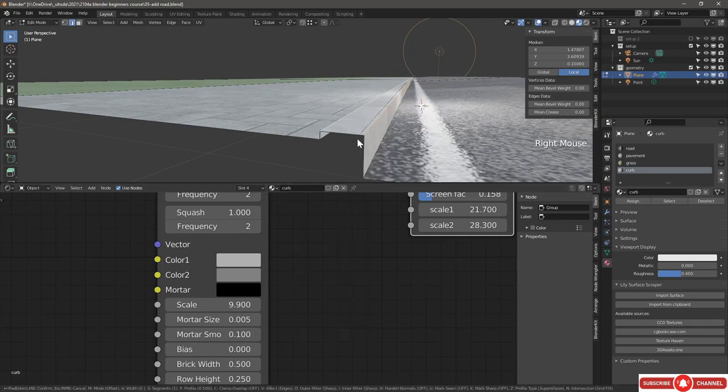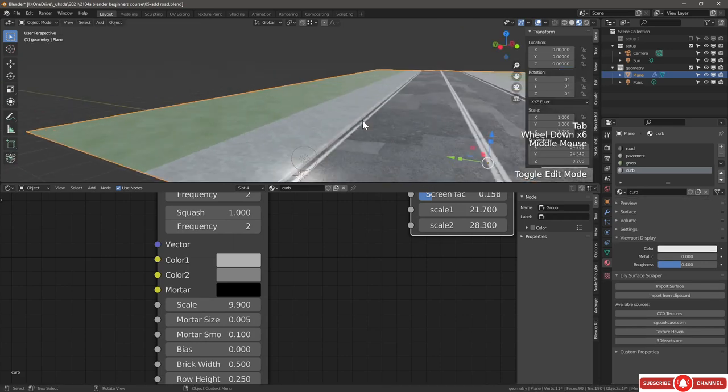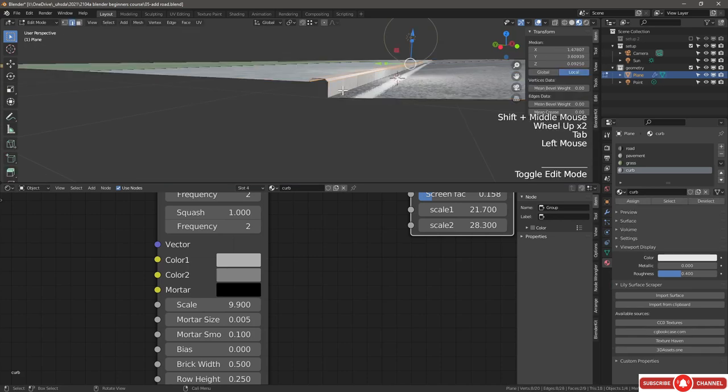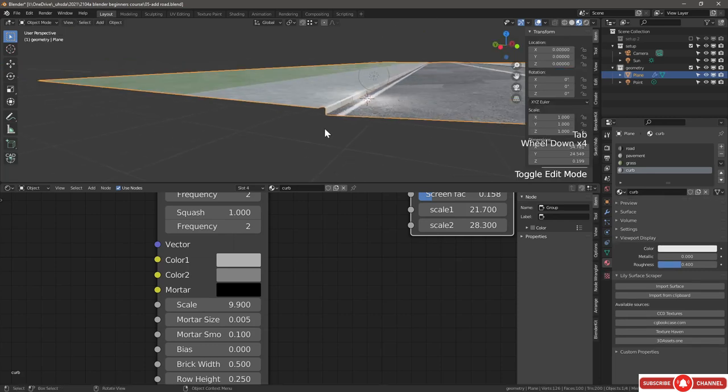Right click, bevel edges. And it's going to start beveling, or we can just type something like 0.03. That's too much. 0.015. Okay, so that just created that nice little bevel edge over there. And we can do the same with this edge. Control B is the shortcut, by the way, for bevel. And we can do something very, very subtle, something like that.